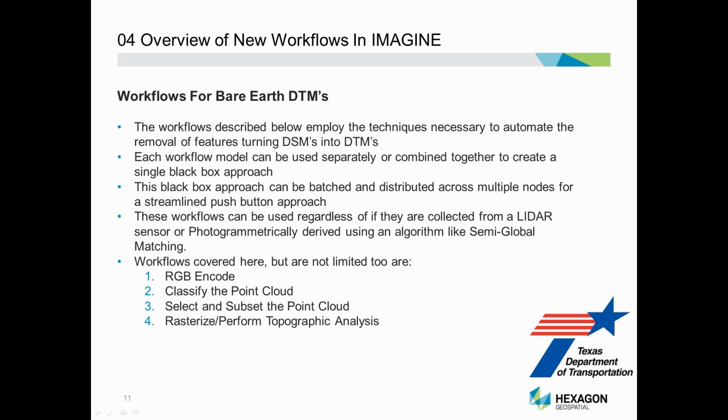So the workflows covered here, there are obviously more workflows that can be addressed and thought of and worked on for your specific application, but in this case we're just going to be showing how to RGB encode the point cloud, how to classify the point cloud, how to select and filter out the point cloud and subset it, and then also to rasterize that point cloud so that we can perform topographic analysis on it using those remote sensing tools I spoke of, and essentially all the other operators available to you in the spatial modeling environment that aren't just LIDAR or point cloud operators. You have the option to use all of them at that point.